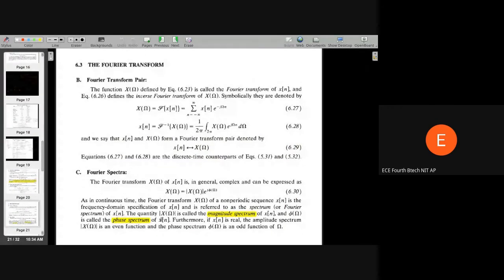The Fourier transform, again, if you think your period is infinite, you get your Fourier transform, and these are the relations. Here it has been represented by big omega, but in many of your books you will see e to the power j omega, or simply omega. But just by context you will know whether it is discrete or continuous time.